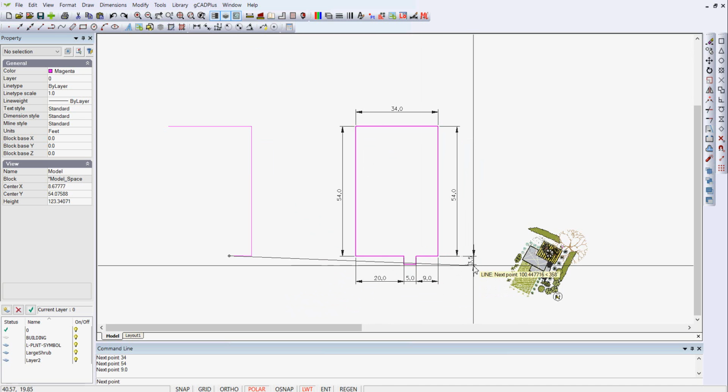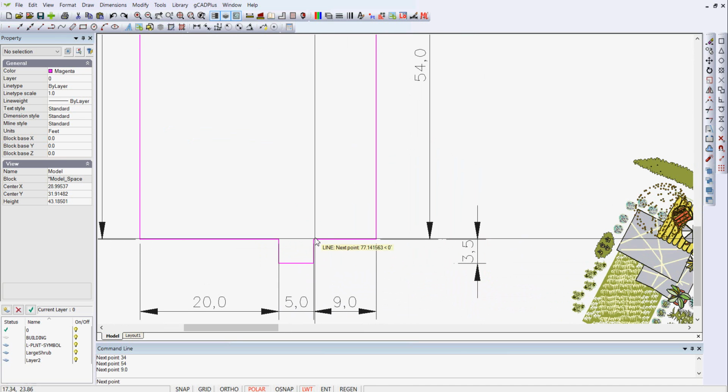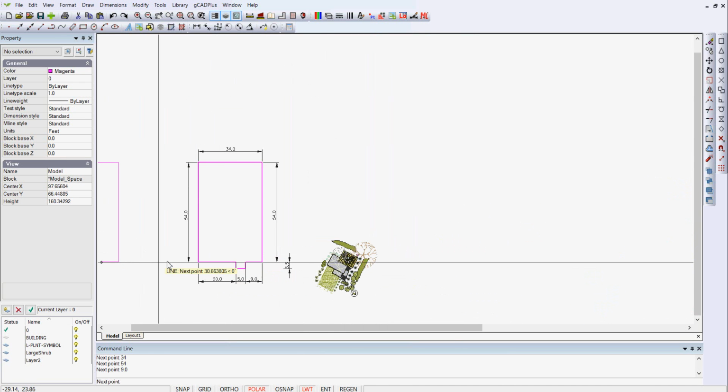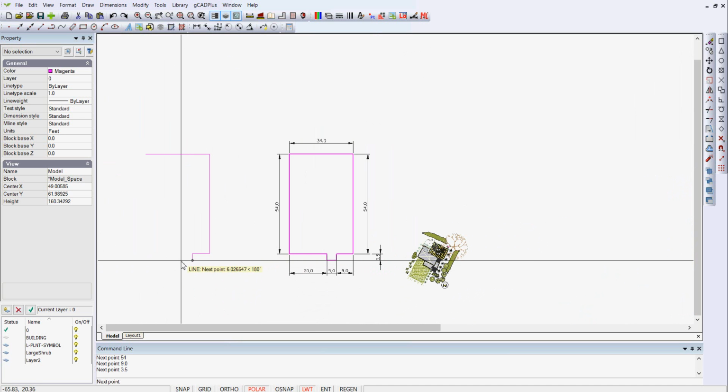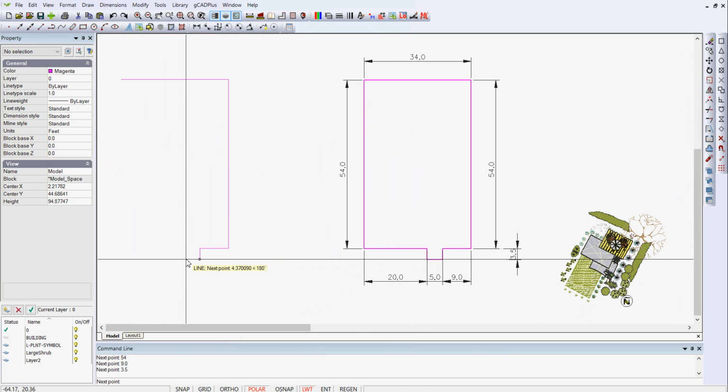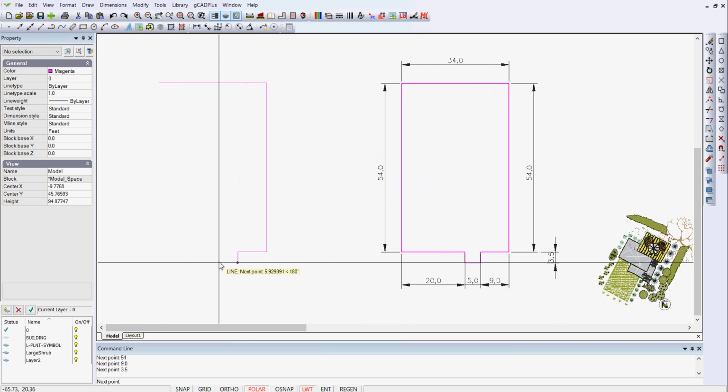If you look over here, 3.5 is the distance for the little porch. So let's move across again. So I come down here, and this time making sure your cursor stays locked in, it's just a matter of typing 3.5. So I'll be taking these sort of measurements from a little mud map that I would have done on site.